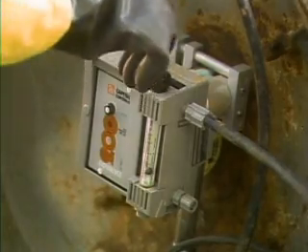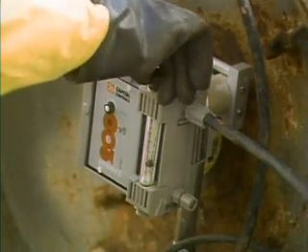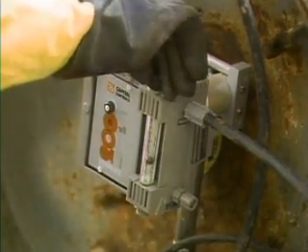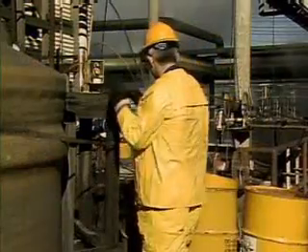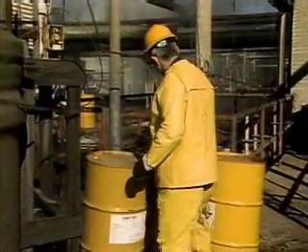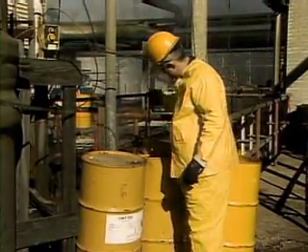Microorganisms can be controlled by adding chemicals called biocides. Chlorine is one biocide that's commonly added to water to prevent slime growths. Chemicals are added to the water in cooling towers for many reasons. You may be responsible for adding chemicals to the water, so you need to know how to do it safely. Many of the chemicals used may be hazardous if they're not handled properly.